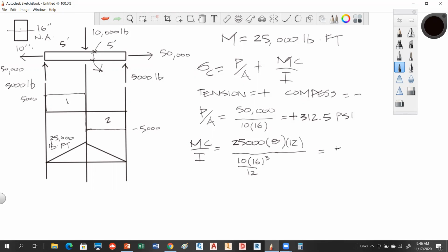It's good to show you that if you're not careful, it's really easy to make a mistake on this stuff. I came up with 703.13. And this is going to be also PSI. See, I would not have been in PSI. I would have been in some funky unit, which would have been incorrect. Okay. Try that now and see what you guys come up with. If you don't like calculating I this way, you could calculate it before you plug it in also. But just remember, this is inches to the 4th. C was in inches. This also has to be in pound-inches. Okay, so units, big thing here, okay?